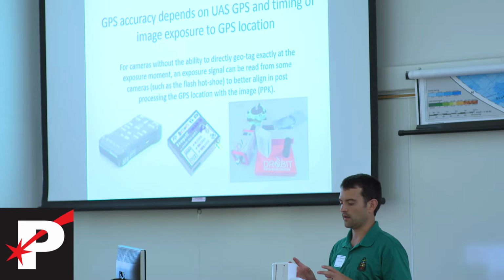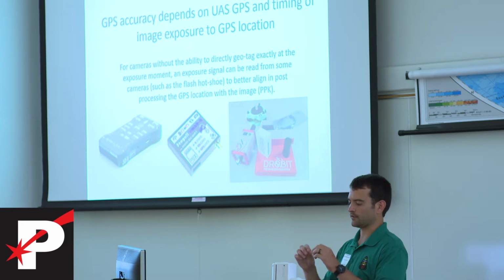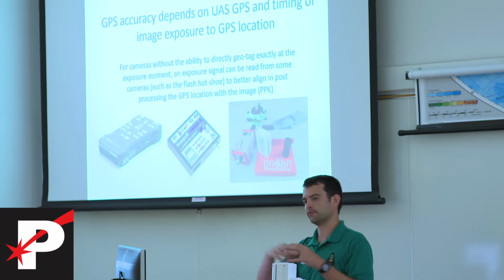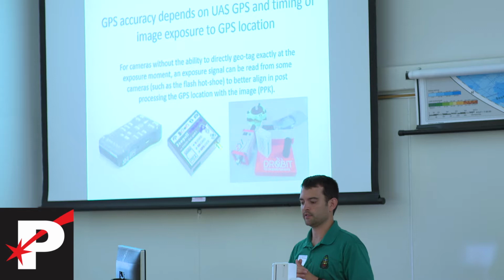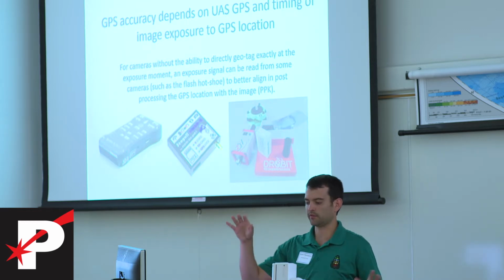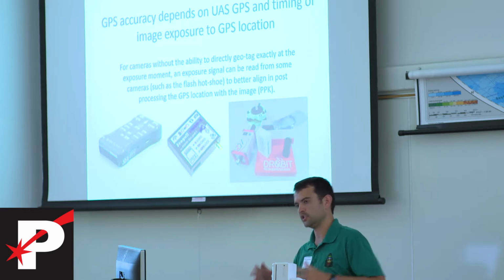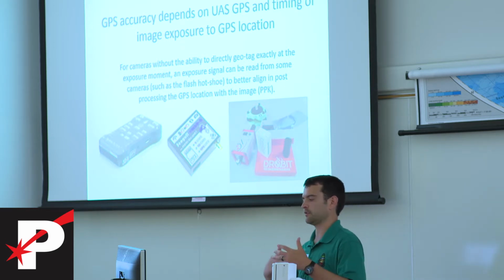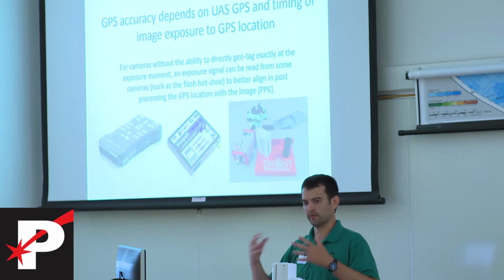If you're concerned about the accuracy within your captured information, you're looking for horizontal versus vertical inaccuracies, and those can obviously be improved with ground control points, but having each image properly geotagged is also very, very important. So these technologies are going to become kind of in the background as we move forward with the drone space, because the drones are just going to do them automatically.